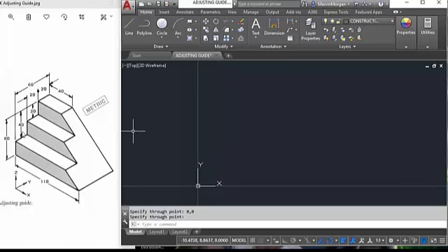At this time, using the dimensions that are provided here, I will provide a series of offsets to make some parallel lines to help form this shape with the two existing construction lines I have. So let's go to the offset command. The first distance I would like to plug in is the overall width of my front view, which is 110. So I'll type in 110. I'm going to click the construction line layer here, and I'm going to click to the right.